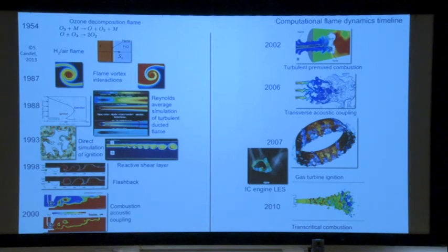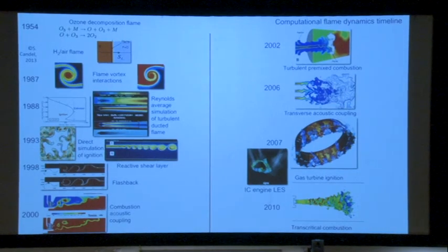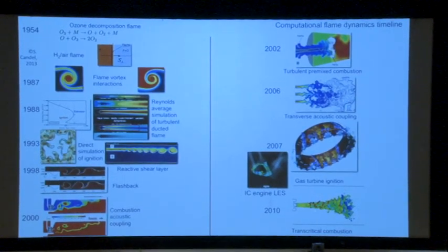This is done now with LES, studying flashback, and these are some calculations of gas turbine combustion using LES. These were done in 3 dimensions, around those years, with a real injector. And these are multiple jets now. And this is the ignition of a full combustor. So as we go on, we now have complex geometry, the injection of a liquid phase, and ignition in this circumstance. This was done at CEFRC.